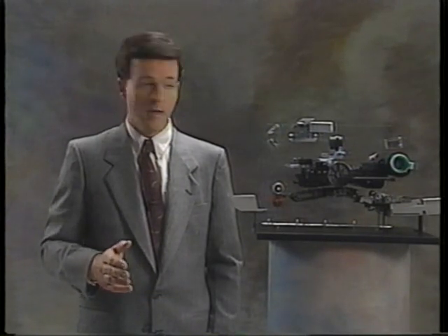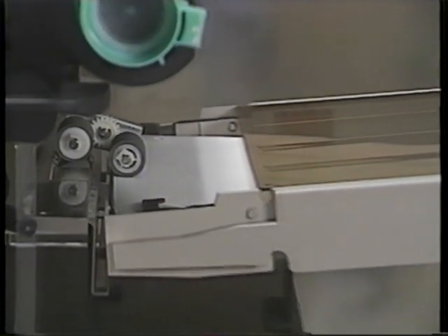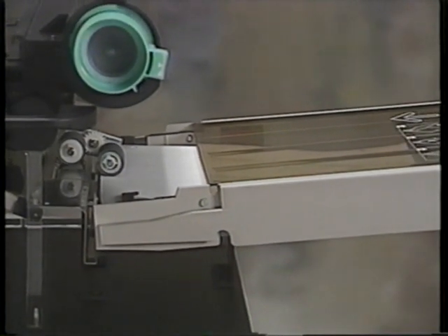While the technology of the paper feed system is by no means unique to electrostatic copiers, it's still a vital part of the copy process. Paper feed systems rely on rubber belts and rollers to grab sheets of paper one at a time and feed them through the copier. Other rollers, or friction pads, handle paper separation and registration.